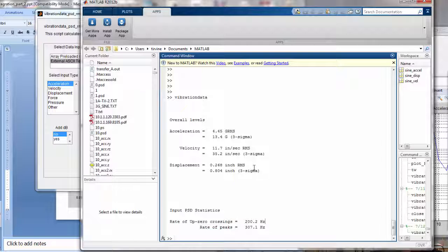So does our shaker, and that's a one-sided, like a 0 to peak. When I say 1.25 inches, I'm expressing that as a 0 to peak level. So does our shaker table have enough stroke to handle that? We may be up against the very edge of our limitation.